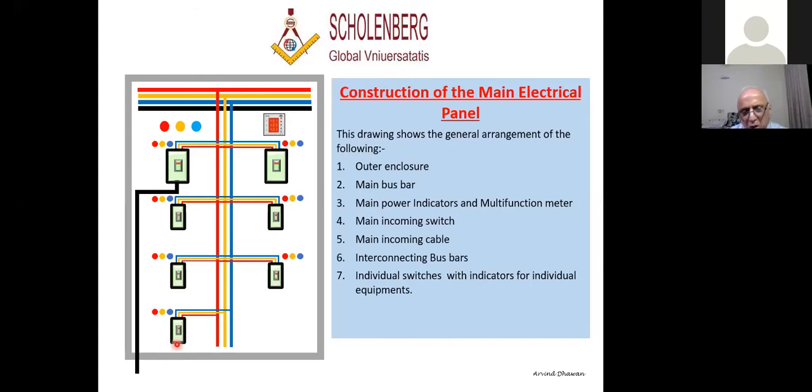You always note in any air conditioning plant, you have an electrical panel inside the plant too. And you'll always have one spare feeder, one spare switch. It's always provided because if any switch gets damaged, you have a spare feeder to take care of that equipment.